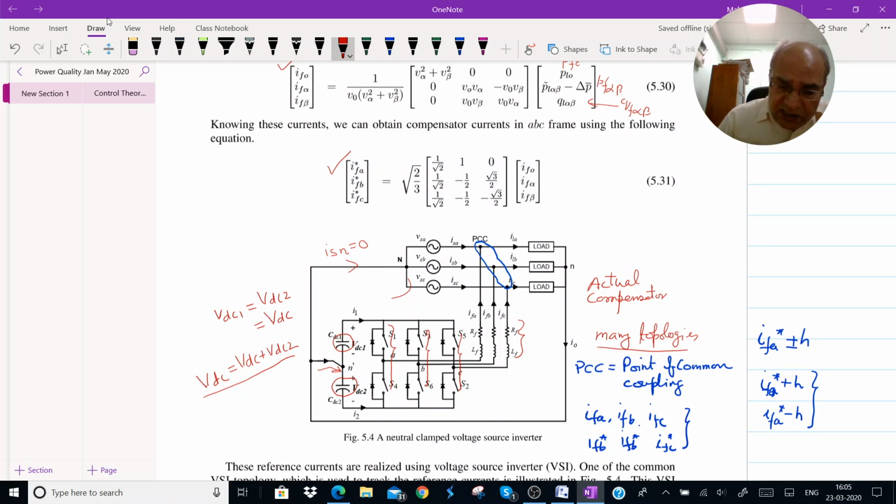Please note the direction of currents that we have taken. We have taken the current IFA going up, and here the current I1 is here. Very important to note, this is I1 here and this is I2 here. So the direction of I1 is this and the direction of I2 is this. The direction of IFA, IFB and IFC are this. With this we can write the first order differential equations for the circuit which starts from, let us say, A, goes like this, comes back here and goes here and goes here and makes a complete path to this capacitance.